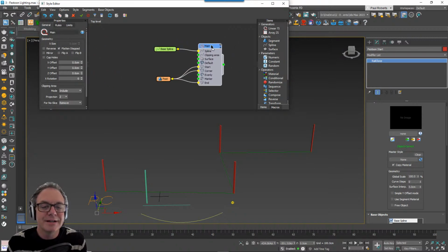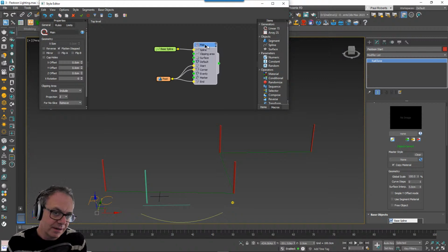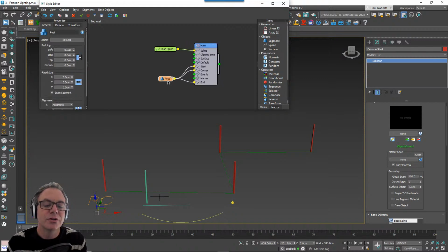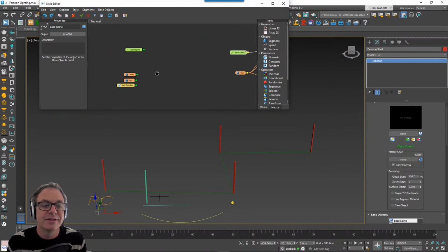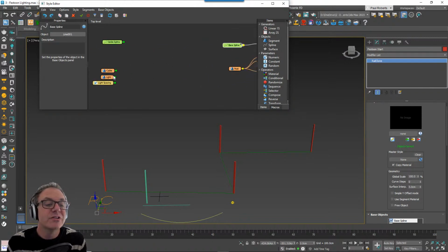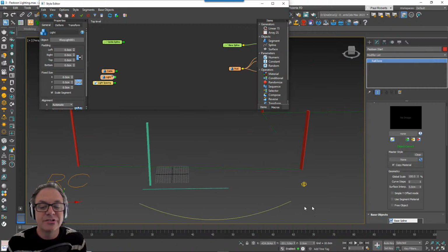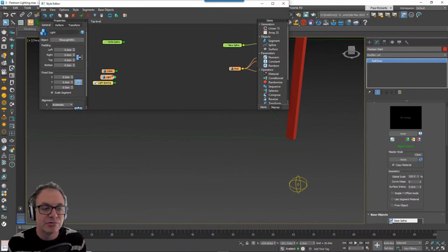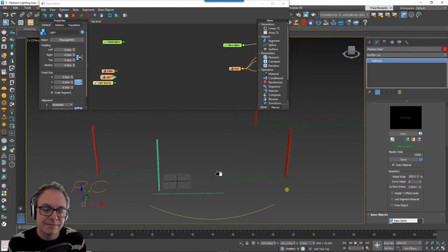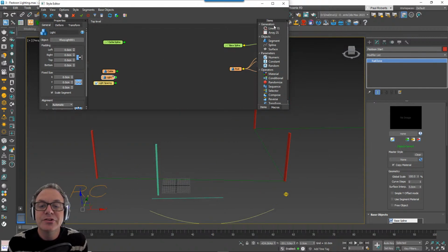Okay. So this one here, I've already got just a linear generator here. I've got the posts wired into the start corner and the end, and I've got a base spline, so nothing particularly fancy there. And I've also added a cable piece of geometry, which is just a mesh, which is here, just basically a cylinder. And I've got a light, which is a V-ray light down here. Now this could be a group, which is a piece of geometry and a light. That would be fine. So what I want to do is to create the cable section separately initially.